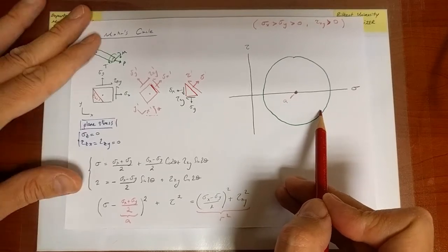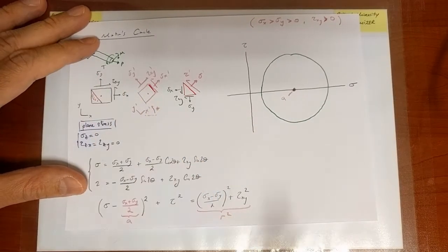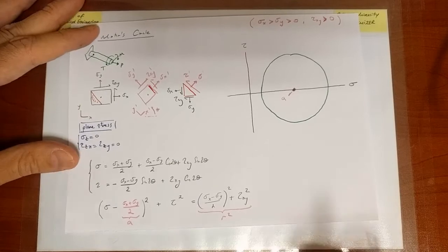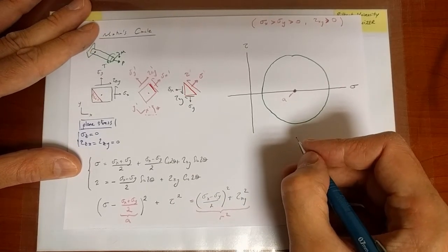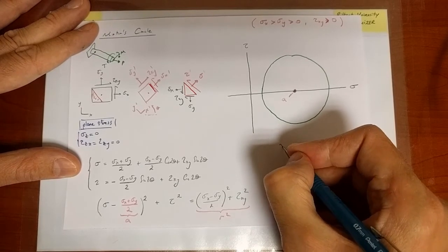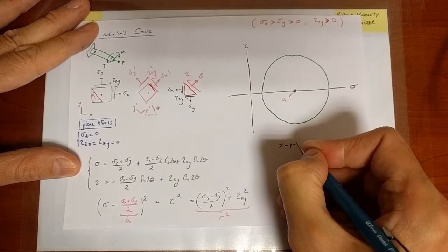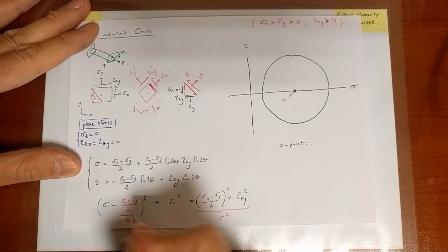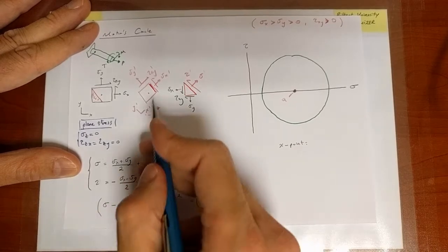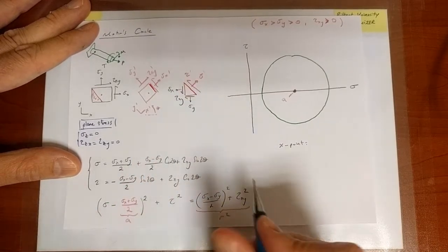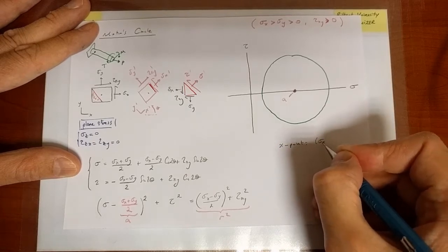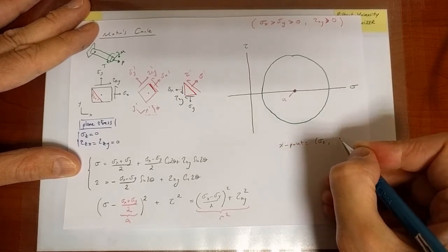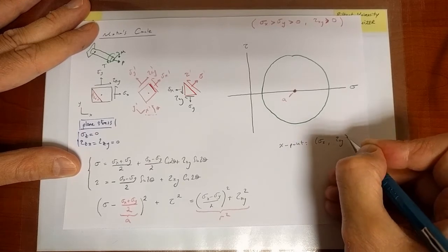The original state of stress has two points. Now, let me slowly indicate that. First of all, there is an x point. The x point, just like any other orientation, will have a normal and a shear component associated with it. There will be a normal stress component and a shear stress component.